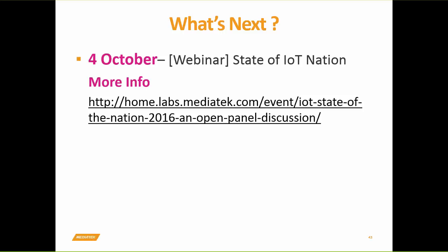What is the difference between 7688 and 7687? I'm assuming we're talking about the HDKs there. The 88 is a much more powerful chip. It runs a full Linux system on it, so it's OpenWRT. Whereas the 87 is a real-time operating system, so it's less powerful, with less power consumption, so you can do fewer things but more power efficiently.